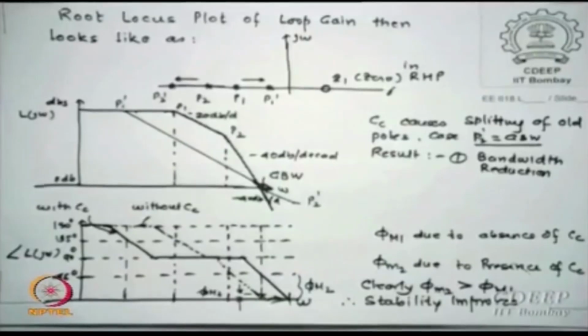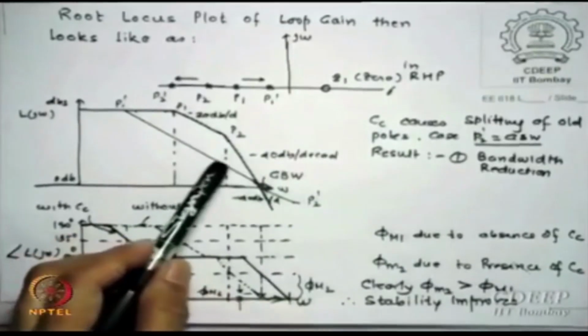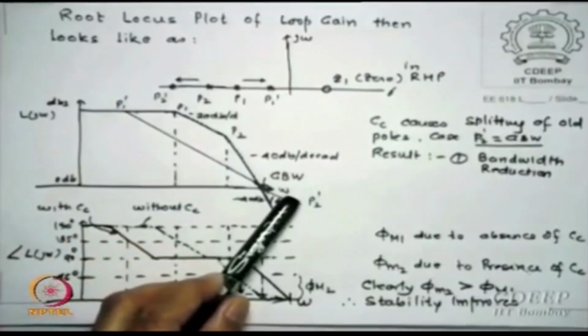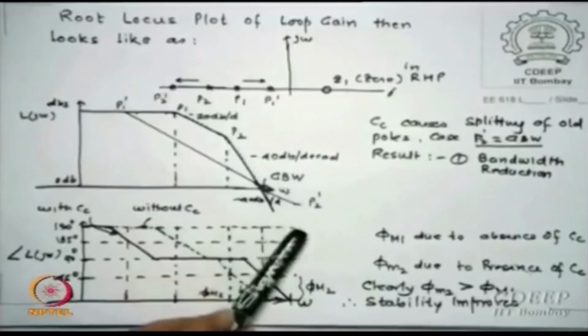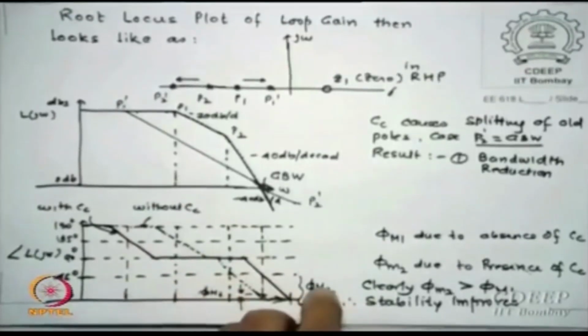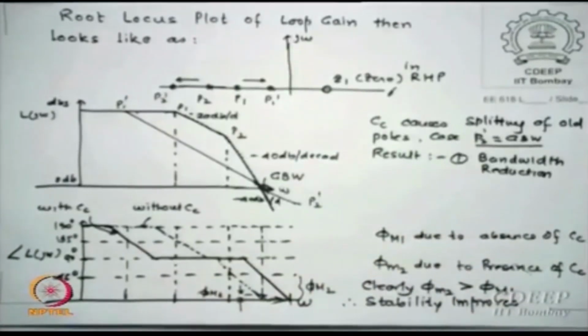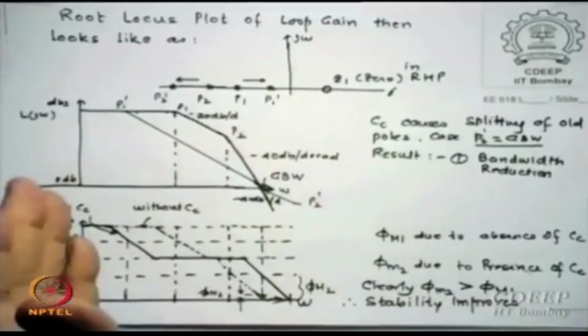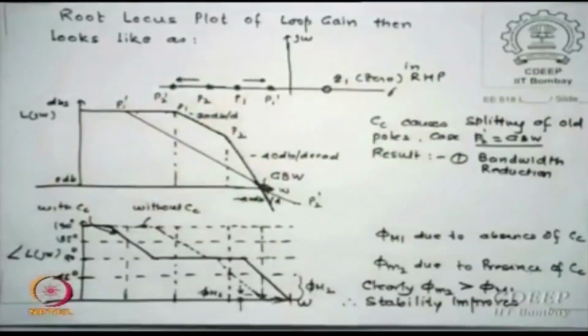So what should I do here? This should continue to have minus 20 dB further, and then the second pole should start, in which case this 135 point will be somewhere here, so the margin will be larger than 45, and then you say, sir, we are safe, okay. So how much to split this pole is also a question, the problem starts somewhere else.